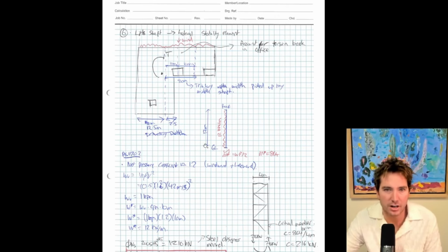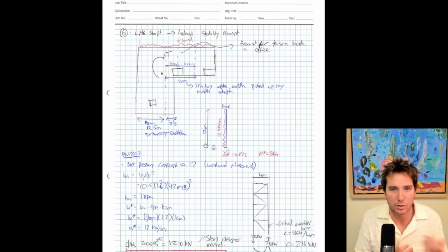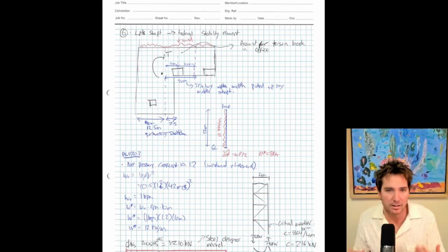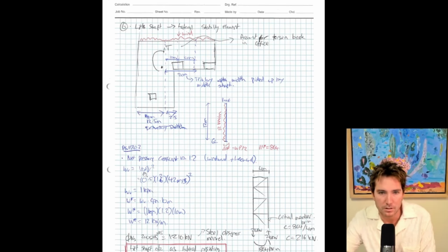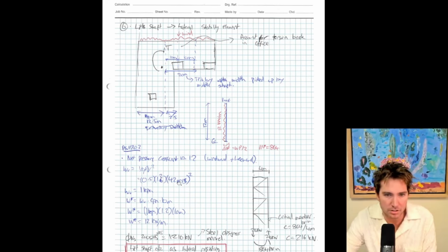Wind pressure, 1/2 rho v squared. Net pressure coefficient. I know you obviously get a wind pressure on your windward and leeward sides, but I've just combined them together quickly and called that a net pressure coefficient. So you do the calc, I get about 1 kPa. That sounds about right for ultimate wind pressures.